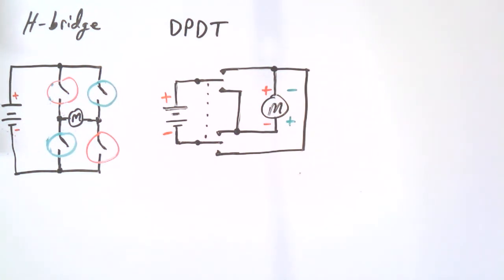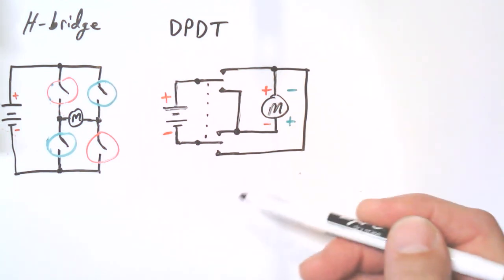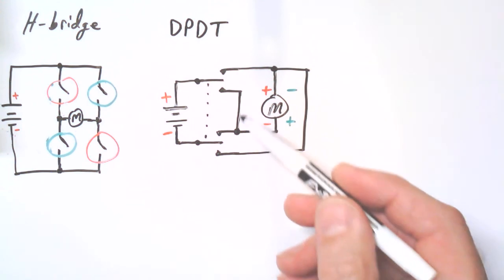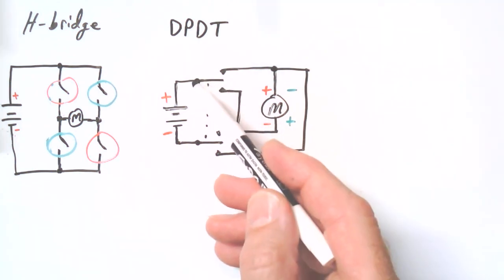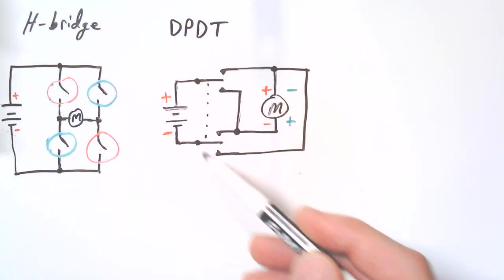And really the next step after you have a good drawing is to even put numbers on the different connection points, and you'll see that done, so that you really don't have to think through any of the theory when you're doing the actual wiring. You want to avoid that. You want to just be able to pick up your cup of coffee and your tools and do the wiring, not have to rethink all of the actual theory. So you would have these numbered, or a letter. This could be A, B, C, D, E, F, and so on.